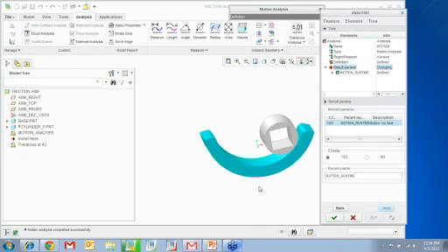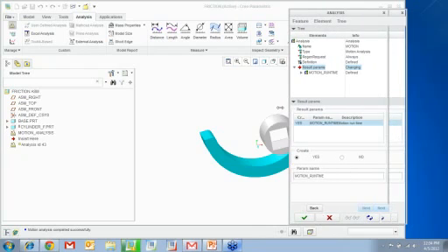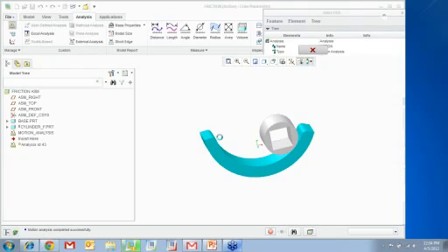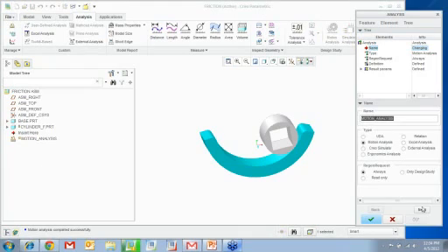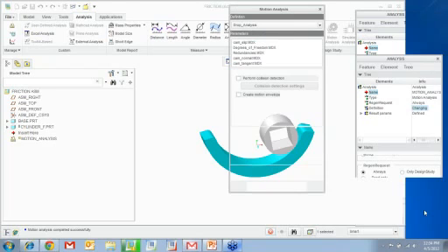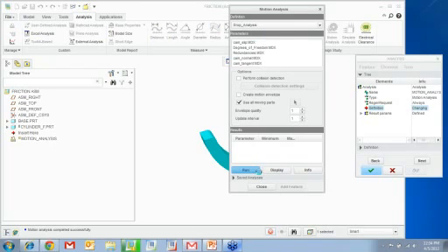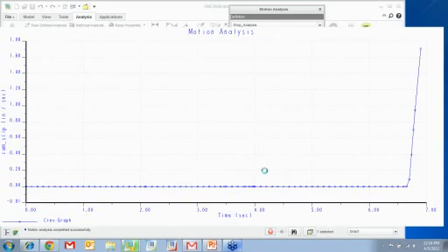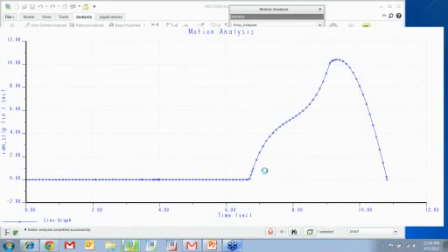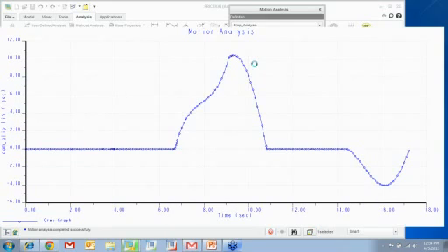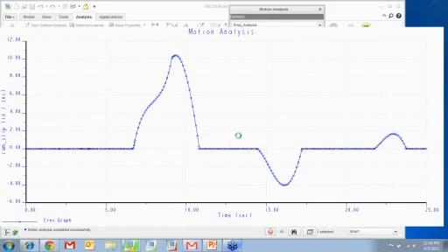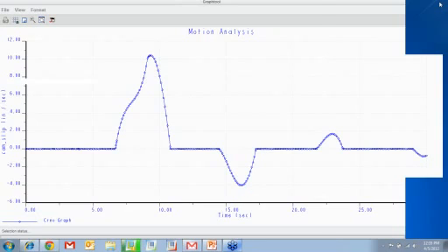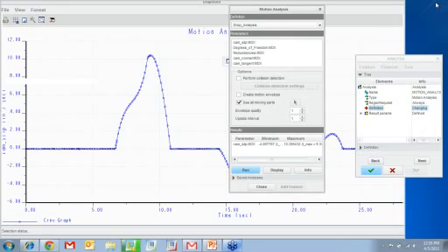And you can close this. So you see different parameters that you can create. Okay. So that's how this particular analysis was created. Okay. Motion analysis. Here are some of the parameters that we have. We're going to run this, and it shows you the up and down. So with respect to performance monitor, now let's say we want to monitor the cam slippage maximum value and the minimum value, right? So now I'm going to say done.